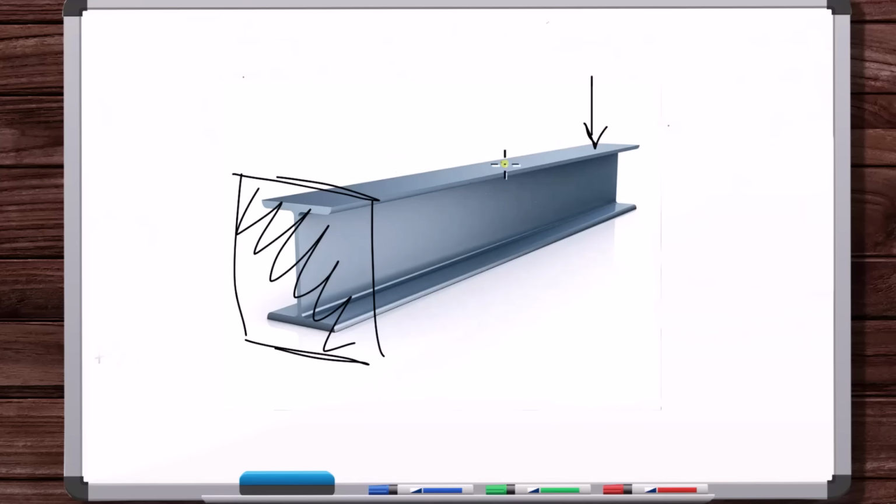And so the cut we made was somewhere around here. Well, okay, if we did a free body diagram, we just unbolted, we didn't make a cut, we just unbolted this here and then brought the entire beam into empty space. We added the forces from the bolts, and we continued to analyze, look for points of contact.